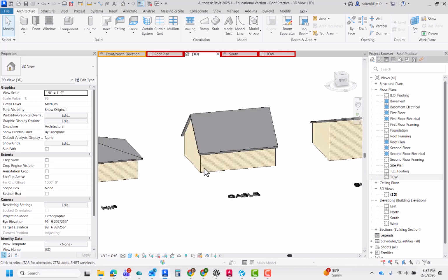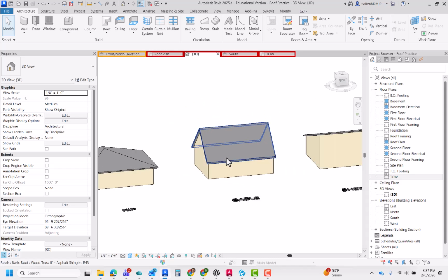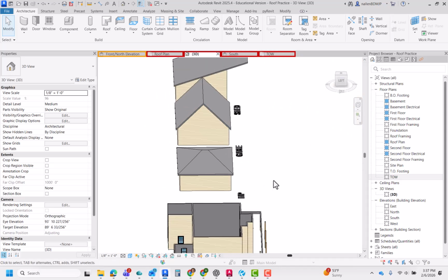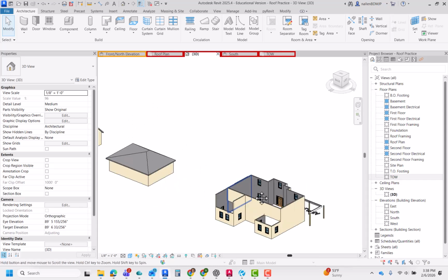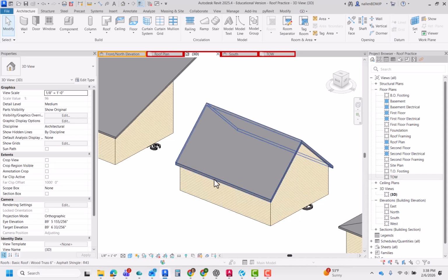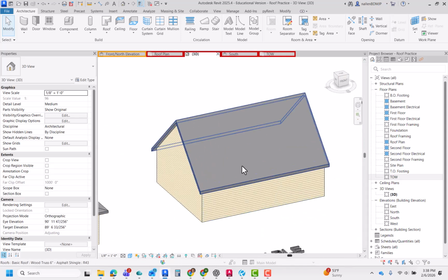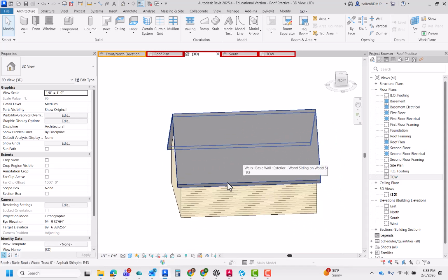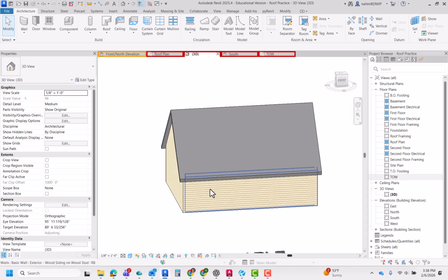And then the second one is that sometimes you need a gable, but you don't have the walls to do it. There might not be a protruding wall. And what I mean by that is over here, these are protruding walls. It's really easy to get a gable there. Over here, what if I want a gable right in the middle? Let's go to the front of the house and let's say that we want one right in the middle. Like there's an entryway here. How do I get a gable if I don't have any walls that I can choose to form the slope? And this gable would be in the middle of the wall and it wouldn't extend all the way from side to side. So it's a very small gable.